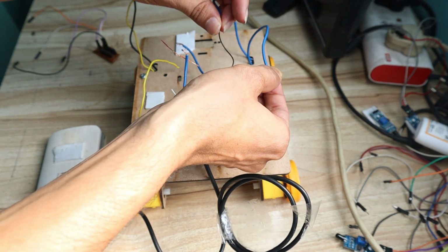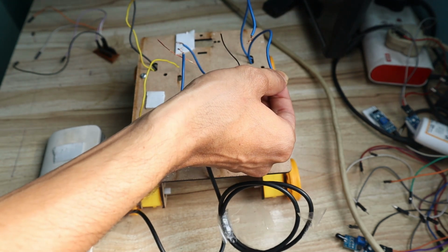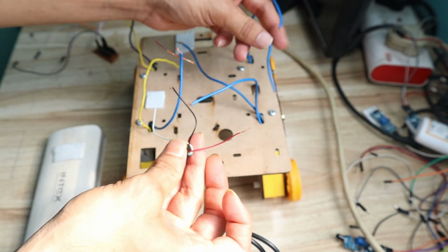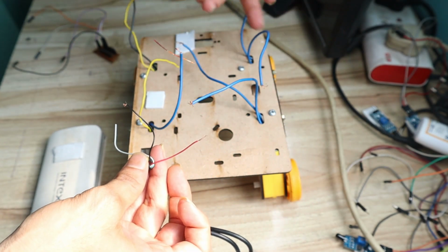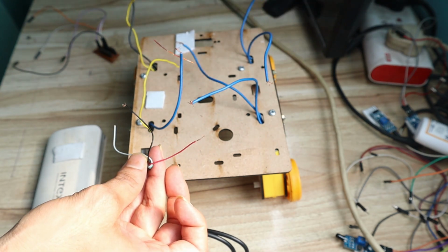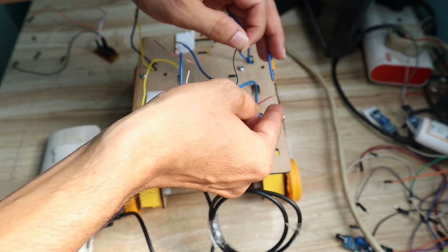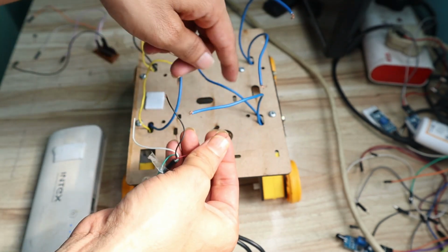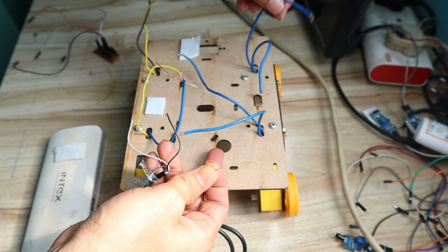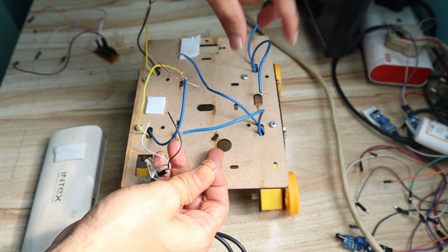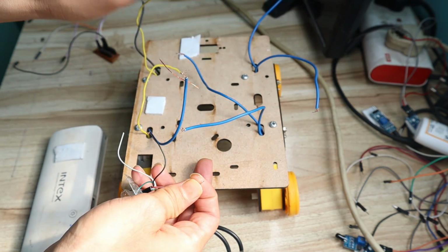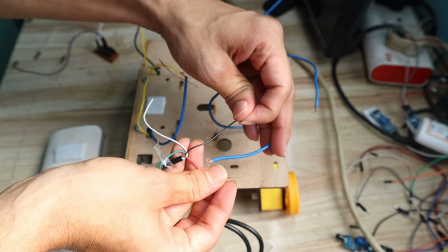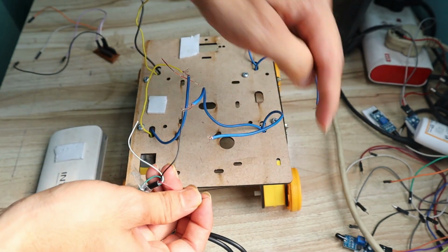You can see my direction is reverse, rotating in the reverse direction. That means when I connect the negative pin here and the positive pin here, my direction is reverse for this motor. Now find out the direction of the second motor. So this first motor we understood: this is the negative pin, this is the positive pin. Same for this motor, you can connect like this. Another motor has 2 pins, connect like this. Again I find this is the reverse direction.